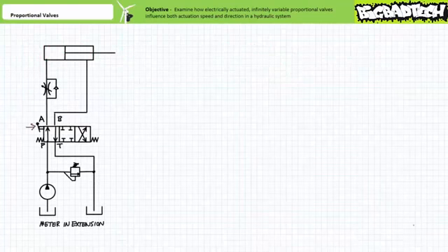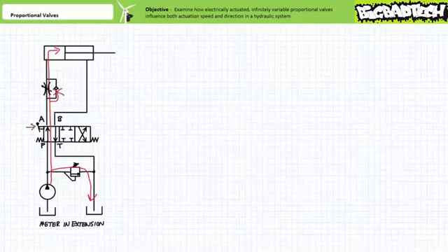Total flow rate available to a system is a function of pump output. Flow control valves are narrow restrictions that throttle flow rate down to the desired value, with the surplus pump output being spilled over the pressure relief valve. While inexpensive, there is a bit of a drawback to this method, because every time a system needs to vary flow rate, the flow control valve needs to be manually adjusted, or multiple flow control valves with multiple switched routes need to be added to this system.